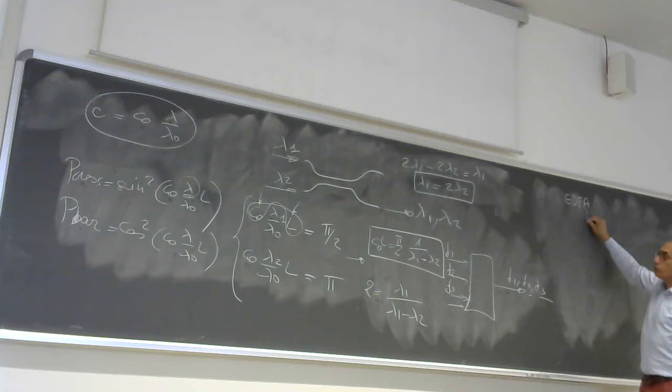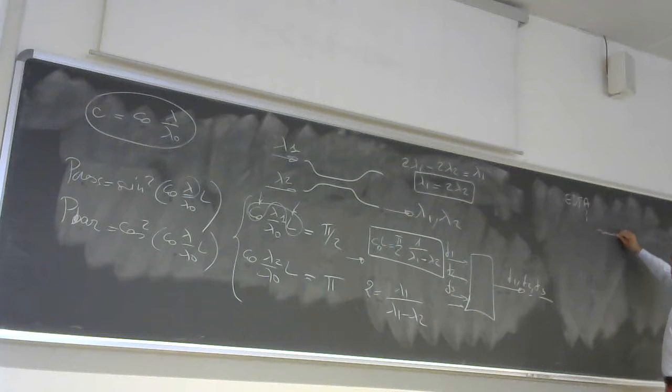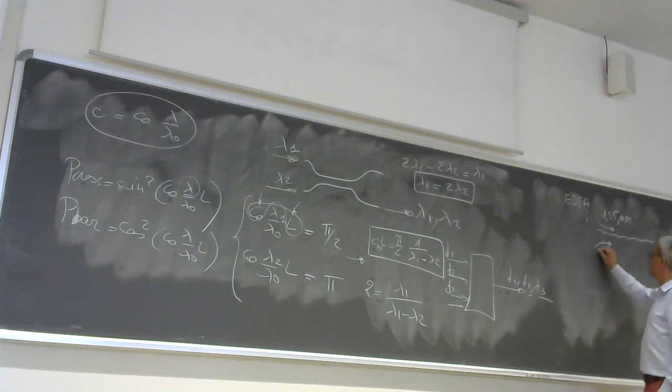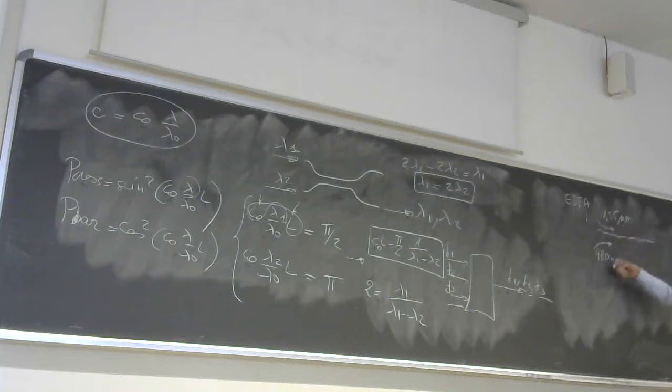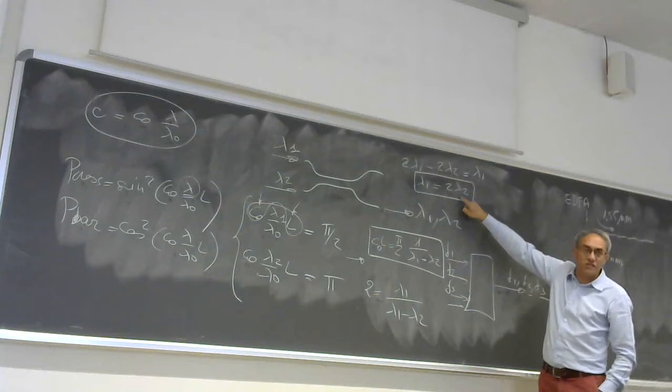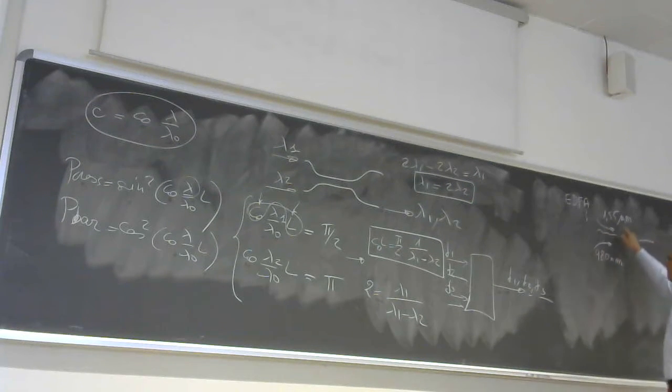The amplification is obtained by propagating in an amplifying fiber the signal at 1.55 micron and a pump signal, so another wavelength that is useful for the amplification, that usually is at 980 nanometer. So you see, far away, this condition is not satisfied, but you are not far from it.